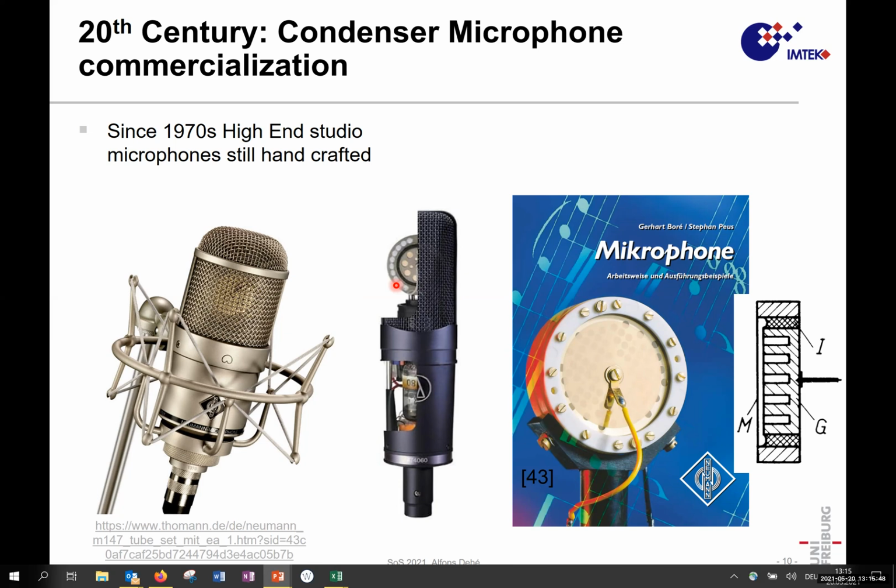The focus is on manufacturing, because if you see here the construction of such a device, you have an insulated back electrode and a metallized diaphragm on top, and you see how they do the metallization. They have a metallized center area of this diaphragm and make the connection to this tiny diaphragm with a screw and a wire to the outside.